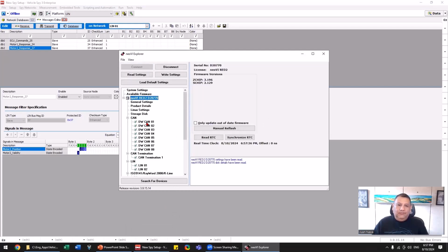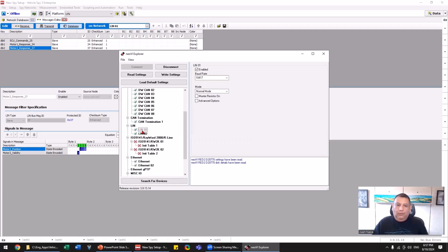So here, since I am not working with CAN, I'm not going to worry about those. And I'm going to go to my LIN channel 1, which is the one that I'm using. And from here, I can go ahead and select the baud rate that I'm using. Now, if your baud rate is not on this list, you can simply type it in. So if I had like 10,000, for example, I can simply type it in. But there's a lot of ones that are already pre-programmed in our device. So I simply just have to turn that off.